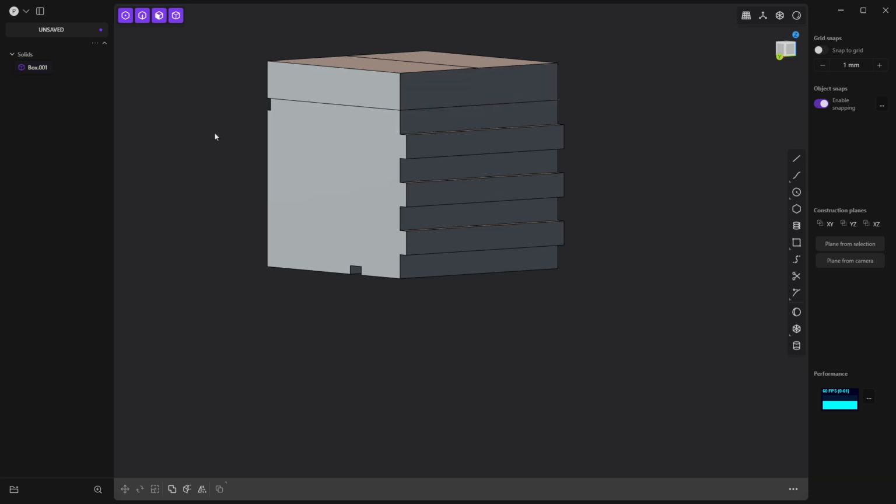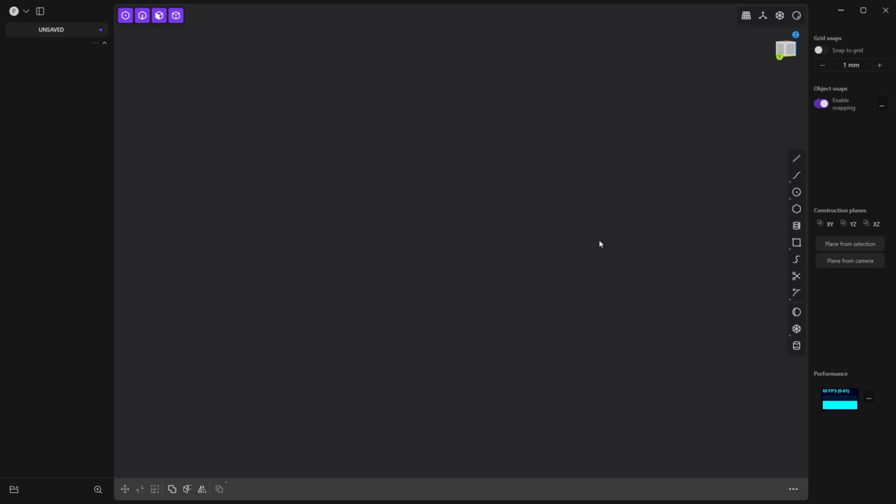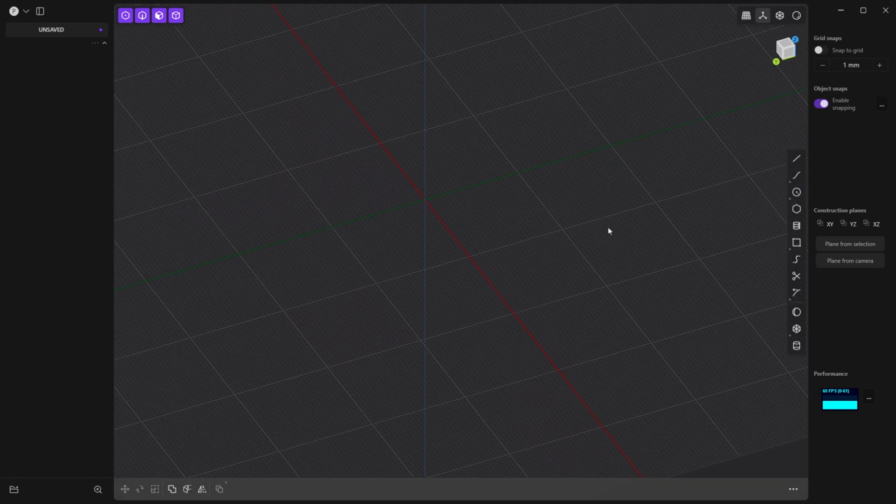So for our purposes, I think probably the easiest way is to build out each individual block and move them into their correct position. It may take a little bit of time, but it's a great way for us to learn how to create these objects, how to manipulate them, and ultimately how to build our 3D model. So I'm going to select this object and hit delete. I'm going to bring back my coordinate system. That way we can see the sketch plane or the default top plane.